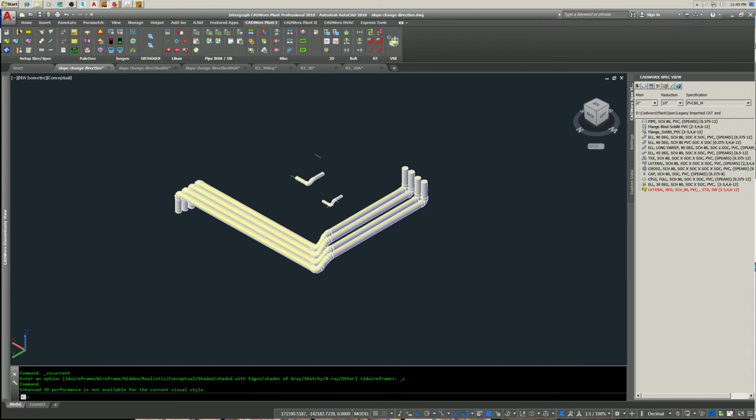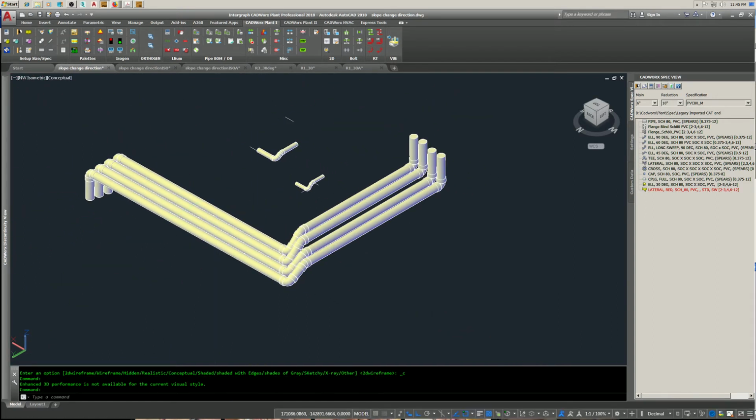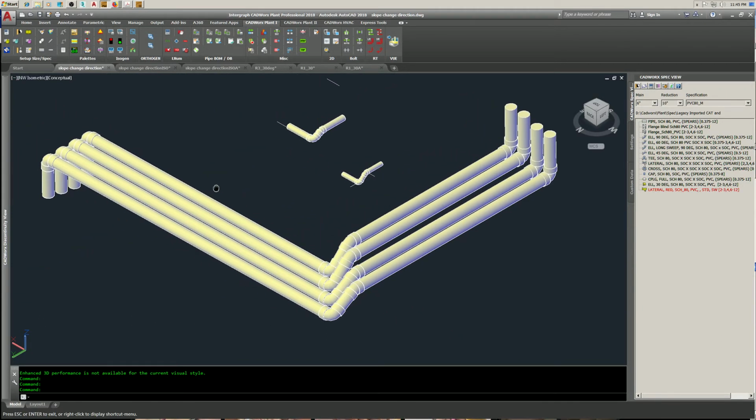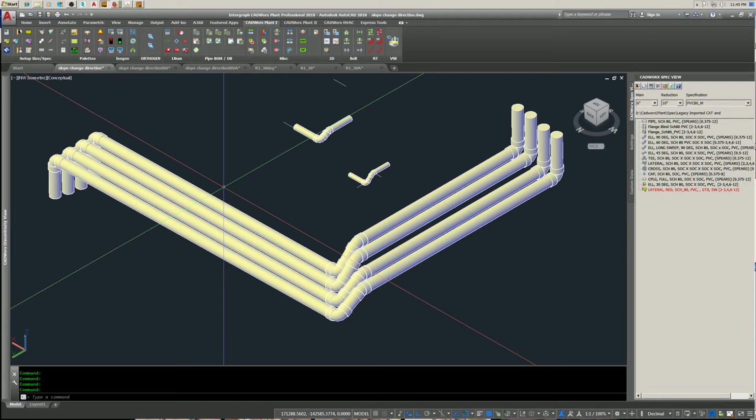The program could crash 15 minutes before you decide to get out and start it up again, and you wind up losing an hour, hour and a half worth of work. Actually, exiting out of the program and starting it up again is a waste of time. Just use Control S. When the program crashes on you, you've got your work saved in your original drawing file. If you can't get to that, you've got a backup file.